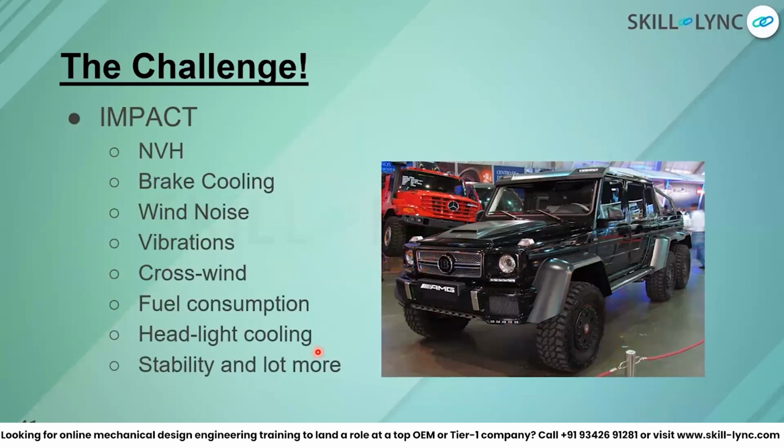Let's take an example: a good aerodynamic design directly correlates with wind noise, because the air is interacting with the truck. Of course the friction or flow separation will create noise also. Then vibrations: if the flow separation is too much, that can cause vibration also. Crosswind, fuel consumption, headlight cooling, stability, and more. So it's not straightforward when you're going for product development.